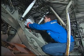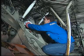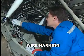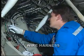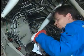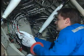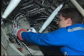During wiring inspection, loose bundles may appear, so make sure that the harnesses are properly attached. Check that separation is maintained. Finally, put adhesive tape on to mark the location of the detected defect.